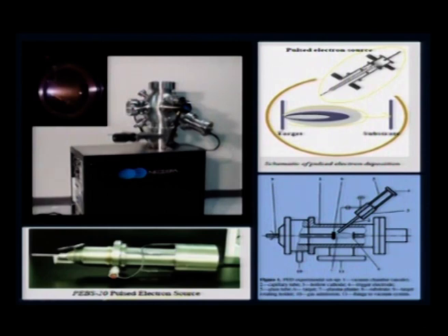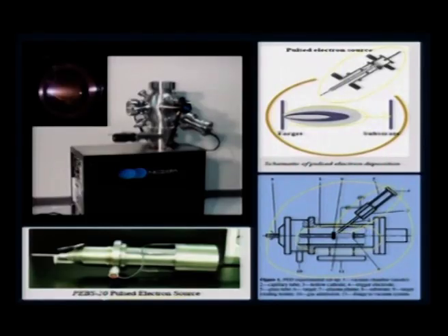Although the pulse electron beam looks very fancy and simple, to take a closer look, these are the elements that are involved. You have a hollow cathode, and this is focused on to the vacuum chamber. This is the vacuum chamber, and this is your PEP source. You have this capillary tube, which is usually a ceramic, and then the hollow cathode here, and this is focused on the target. So critically, although it is simple, the making of the PEP source is tricky stuff, which is the most important element of a PED chamber.